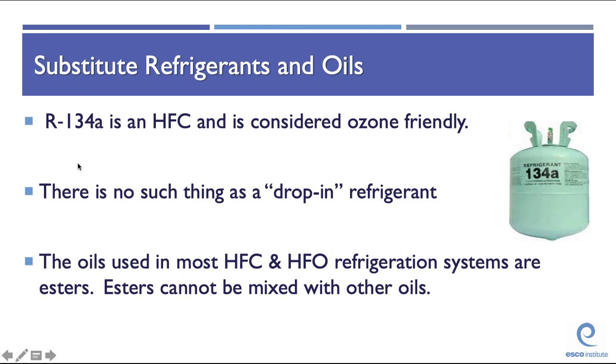R134a is an HFC and is considered ozone friendly. There's no such thing as a drop-in refrigerant. The oils used in most HFC and HFO refrigerants are esters. Esters cannot be mixed with other oils. So even though R134a takes the place of R12, it is not a drop-in. It's also important to remember when leak testing an R134a system to use pressurized nitrogen.